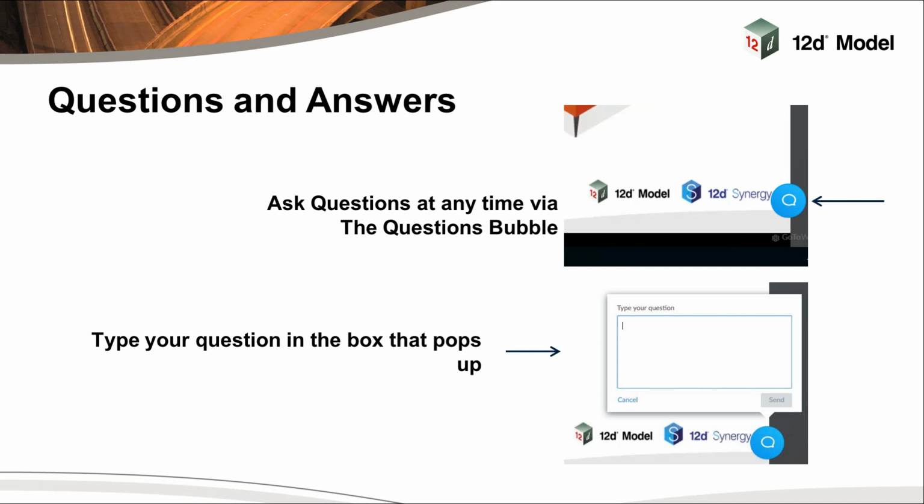So you could continue that along a long alignment, whilst we don't dynamically, if you want the bottom half of the plotted page to be a section plot, that would still take a little bit of manual manipulation, like you have to do anyway in traditional CAD formats. But let's say you've got 10 kilometers and you want to do a 1 to 500 sheet, you can do the plot frames along a string. That'll place 20, 30, 40, 50 plot frames along that alignment, which you can then manipulate, set up, and then use that as a special chapter output. And the advantage of that is you don't end up with 50 items on the tree on the left-hand side. You end up with one special chapter item, which is referencing that plot frames model.